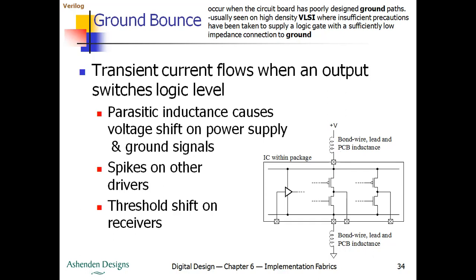Why? Because these spikes are the main cause of the unintentional formation of inductance, the so-called parasitic inductance. Hence, by avoiding the spikes using this bypass capacitor, we get minimization of the ground bounce problem.